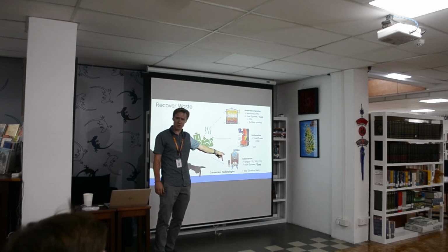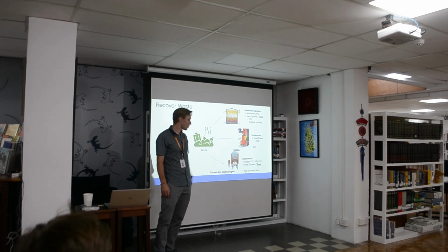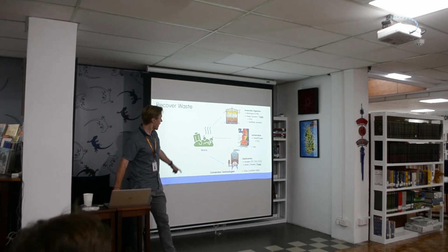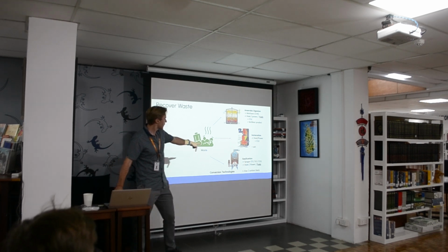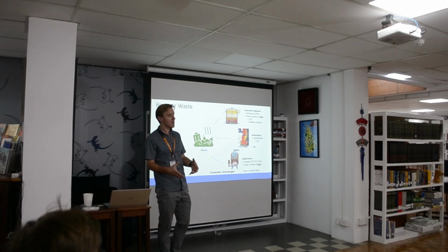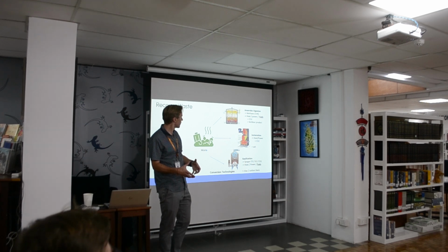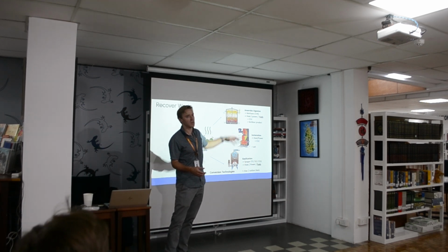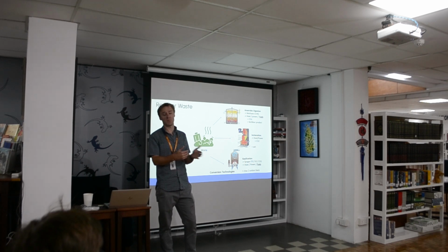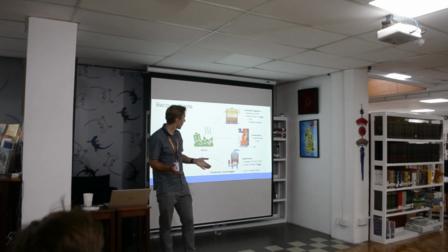And there's another one down here, which is a bit more interesting, called gasification. Has anyone heard of gasification before? No? What you can do with gasification is produce a different kind of gas called syngas. Instead of burning it, you heat it up to a similar temperature so that the matter breaks down, and it doesn't combust. The reason it doesn't is because you don't allow any oxygen into the process. And what happens is you get a gas coming off the top of it, called syngas.